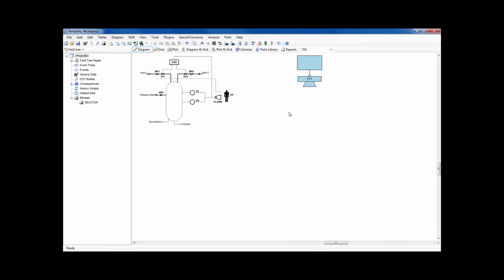Okay. Now, some guidelines on building the fault tree. When I described the safety shutdown system, I described it in the forwards perspective, starting with what happens and then what follows next. The reaction occurs, the sensors detect it, they send a signal, the valves shut. That's the way it's supposed to work.